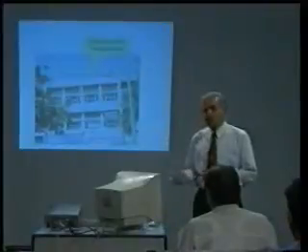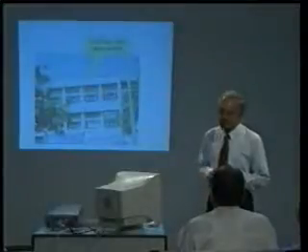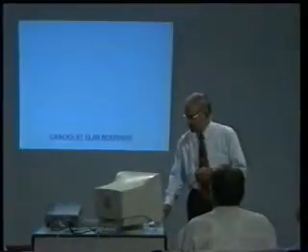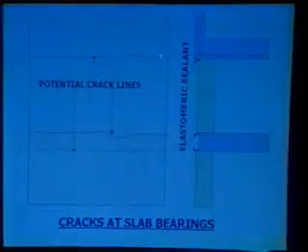Now, this is a very commonly observed sight, gentlemen. If you notice, you have a crack at this junction. Now, this crack between the parapet and the roof slab can very easily be avoided. These are the potential crack lines that you already know, in the elevation. This is the parapet and the roof slab junction, and these are the edges of the lower slabs.